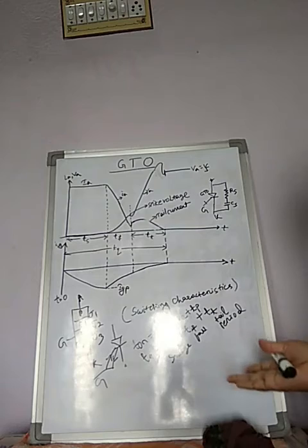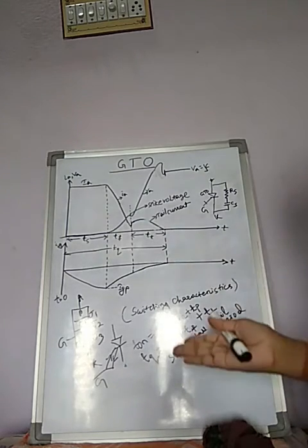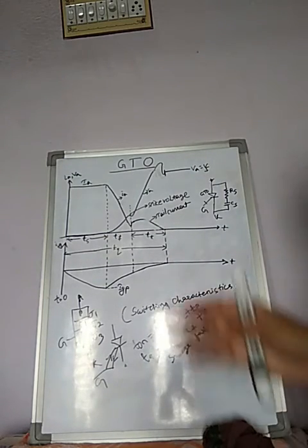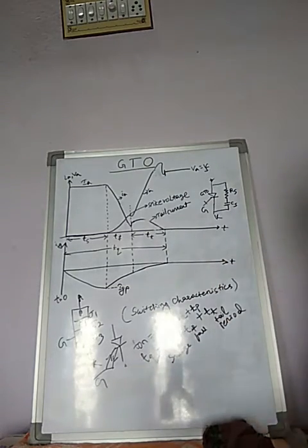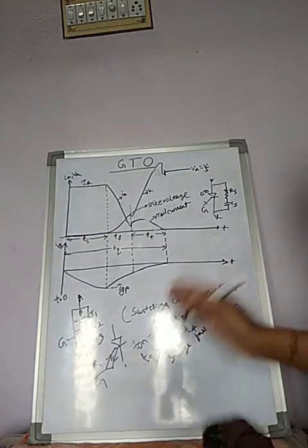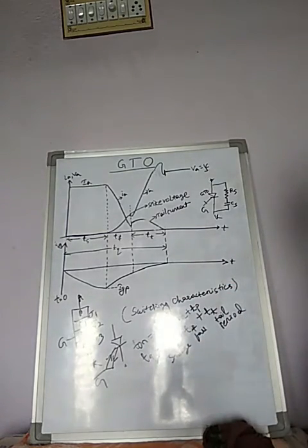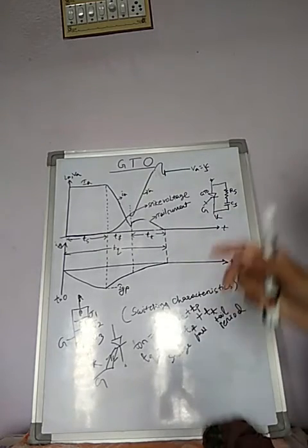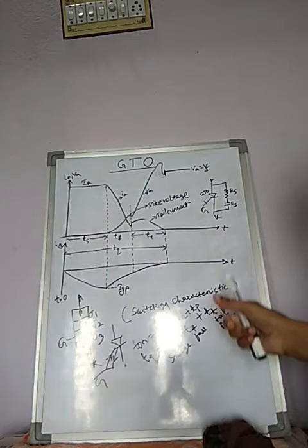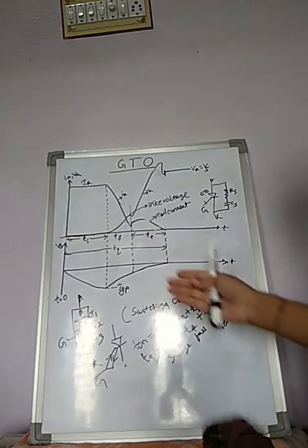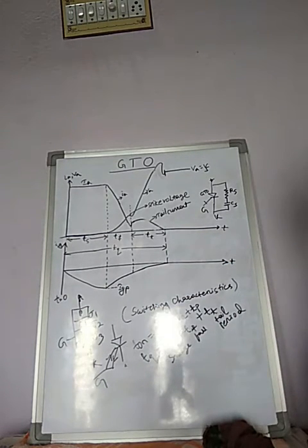So when we use this device in an inverter circuit, the disadvantage is no more a concern. Which disadvantage? That its reverse voltage blocking capability is less than the forward voltage blocking capability. So this point is of no concern when this device is used in an inverter circuit.